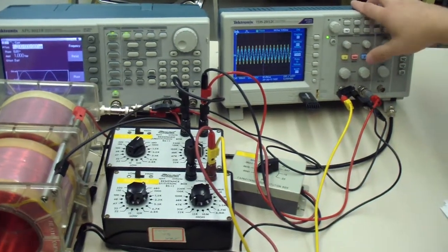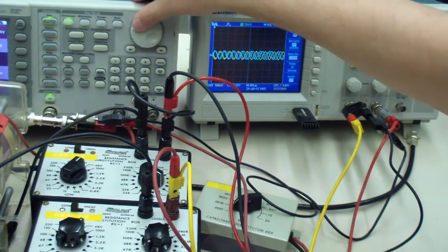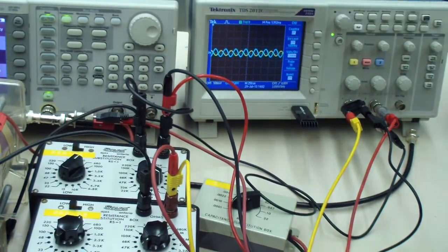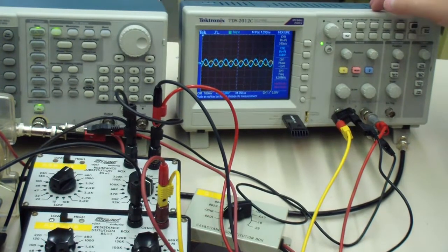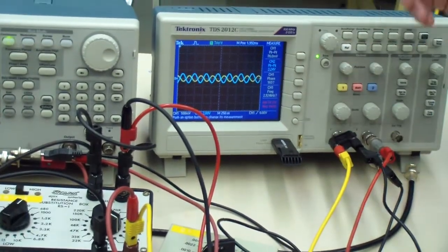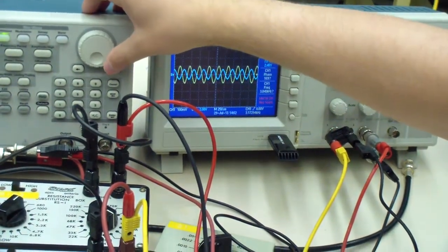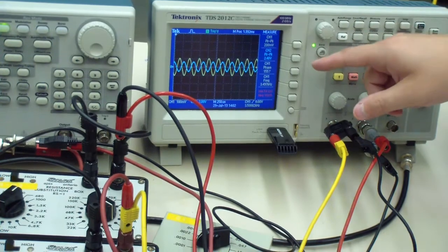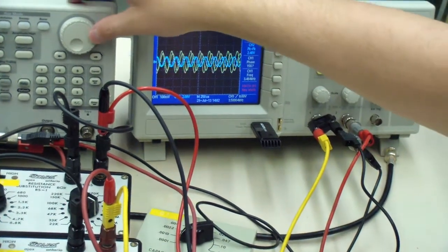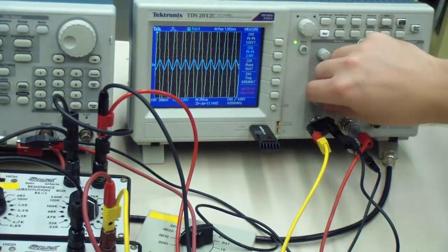Set the function generator to a frequency below both resonances. Record the amplitudes, increase the frequency, and repeat until you've established complete amplitude spectra for both capacitors. Note that you should gather more points near and between the resonances. Also note that if the signal goes off-screen, the oscilloscope will display an unreliable value with a question mark, and you should adjust the scale.